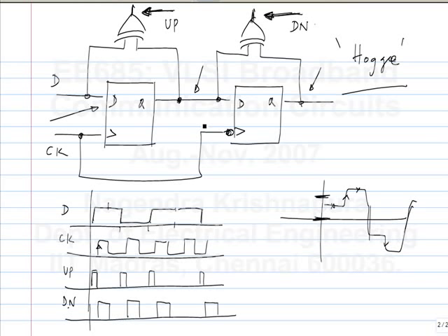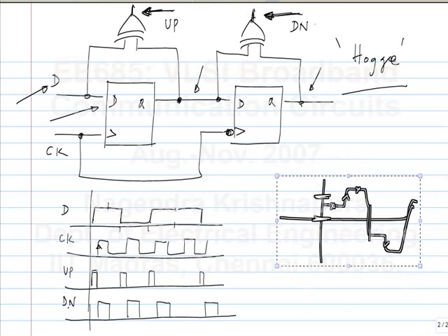But you can just feed PAM4 data here and it will lock. But the properties of the phase lock loop will be somewhat different, because you have lost a certain number of transitions. If all transitions are equally likely, then you have lost half the transitions. What is the effect of that? So let's say, what do you think will happen?